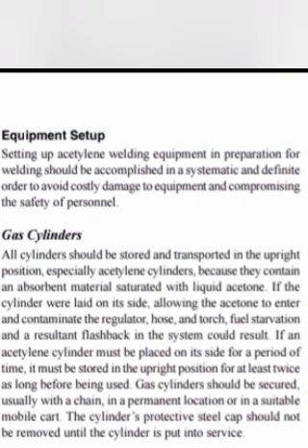Equipment setup. Setting up acetylene welding equipment in preparation for welding should be accomplished in a systematic and definite order to avoid costly damage to equipment and compromising the safety of personnel. Gas cylinders. All cylinders should be stored and transported in the upright position, especially acetylene cylinders, because they contain an absorbent material saturated with liquid acetone.